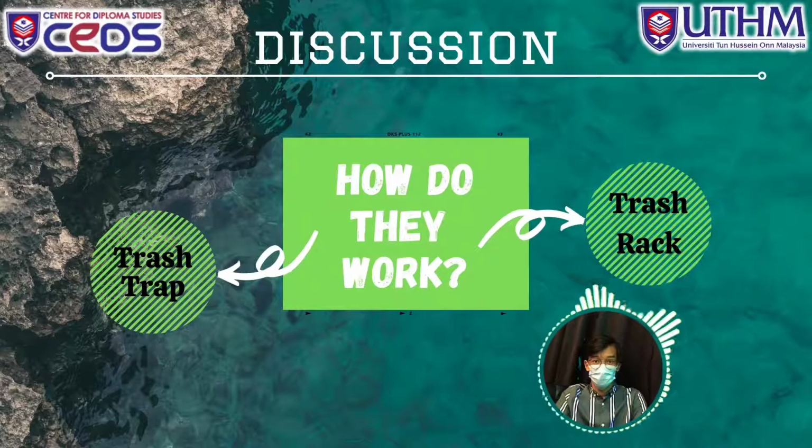Trash rack. In many cases, hydro dams use their intake to take water from a lake, river, or reservoir for power generation. Water can bring a variety of objects into the system, including logs, stumps, wildlife, and waste, which can be hazardous to the plant infrastructure. The trash rack is positioned to prevent debris from entering the system through the intake.